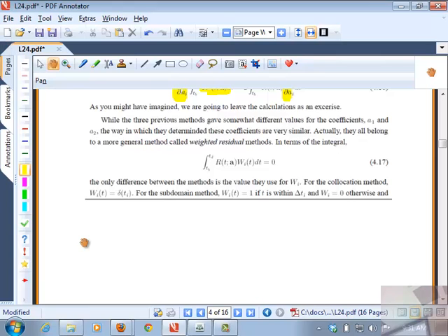All these essentially fall into this category. Okay. Method of weighted residuals, where the weighting function has different choices, delta function or subdomain, break it into two or three domains, and you're using essentially a very small number of unknowns, 2 degrees of freedom, 2 unknowns. Okay. In COMSOL, you typically use 20,000 or 30,000. But the process is very similar to what's going on here.